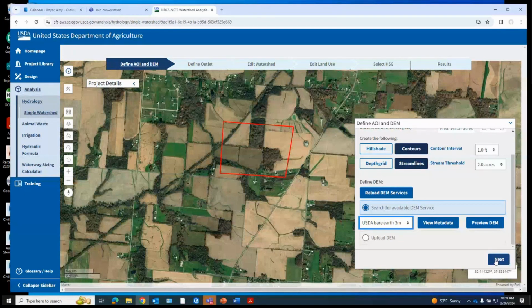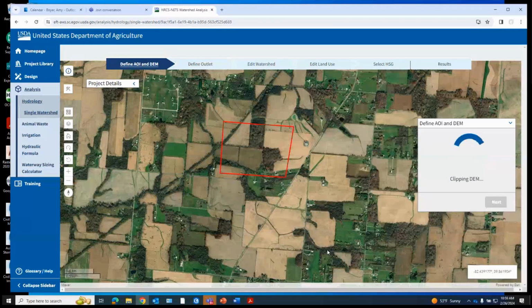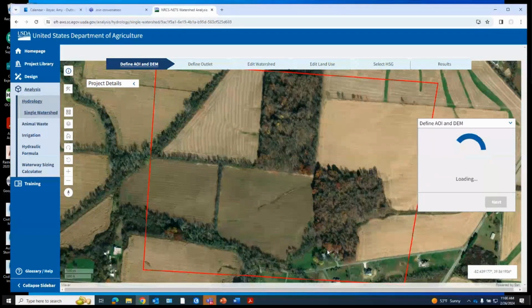Now, this might take a minute to run. The one thing you want to know is this is not going to be that really new DEM that you get off OGRIP. So that's one of the things you want to think of. If you're in an area where you know we've had a lot of construction work, we know that those contours have changed, this is probably not the program you want to use. You want to default back to the ArcPro.